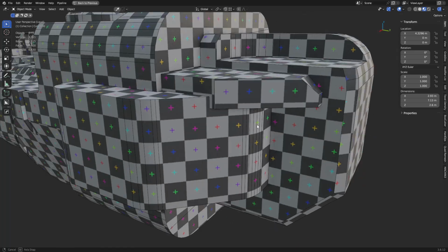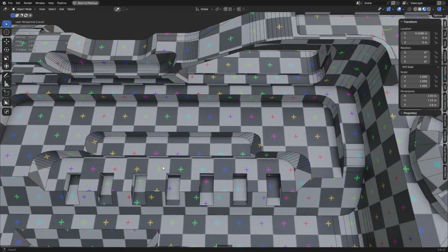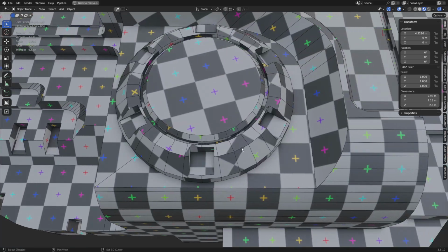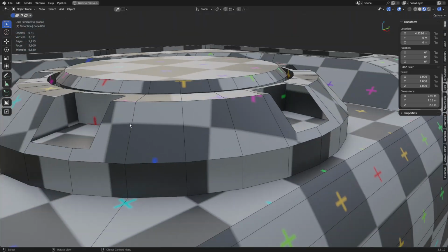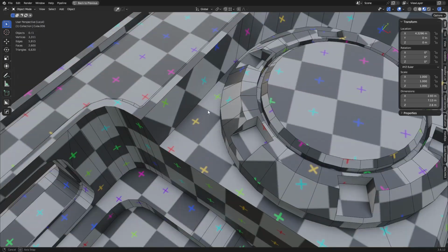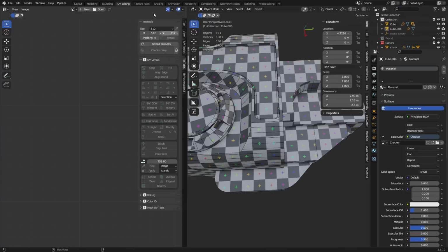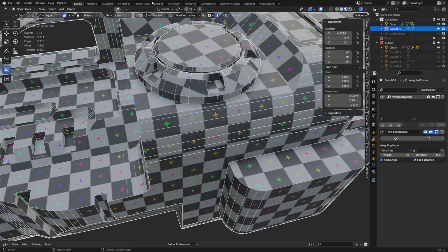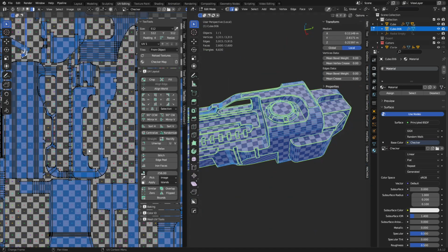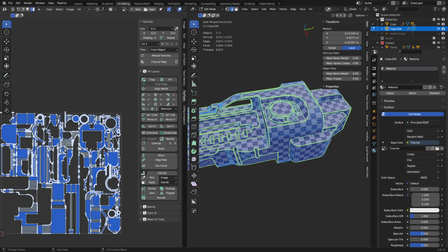And yep, so if it looks good, there's no distortions, then we should be okay. We're looking to make sure they're just squares for the most part. Sometimes they might rotate and sometimes it might have little slight distortions. Don't get too worked up over it. It's not really worth it usually. Just trying to make sure it's well enough. And so this should be how fast it kind of goes as well. Like you should be kind of flying through these things. And if you don't want to see the checker grid in the background, you can exit and just do that. Okay, as long as it's a square texture, you're fine.